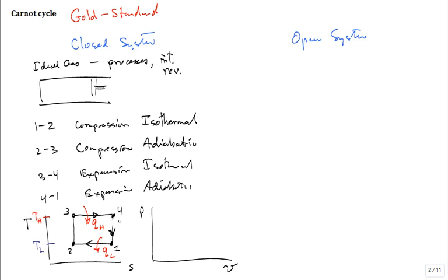1, 2. Really, I encourage you. So what would it look like? Remember on a PV diagram, the ideal gas equation, and then you stop at 1 to 2. That's an isotherm, your low temperature isotherm. Maybe I want to sketch it in, showing you this is TL. And then you're going to have to jump up to the high temperature isotherm, TH, on a PV diagram for an ideal gas. And when you jump up, you get to 3, and then you expand to 4, and then you jump back down. You're jumping between those two isotherms on a PV diagram.